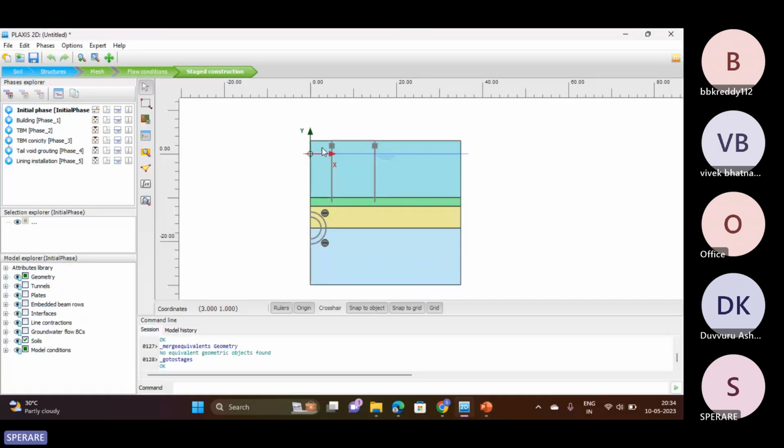Yeah, I agree when it is a gravity loading, when you assume that the building is there in the initial stages. But when there is no building, it's plain soil, then you have to go with the K0 procedure. Okay, so maybe assume that here I'm not considering the building. Now, which procedure will you follow? Assuming that I'm not considering the building at all over here, now, is it a K0 procedure or a gravity loading? K0 procedure. Okay, fine.